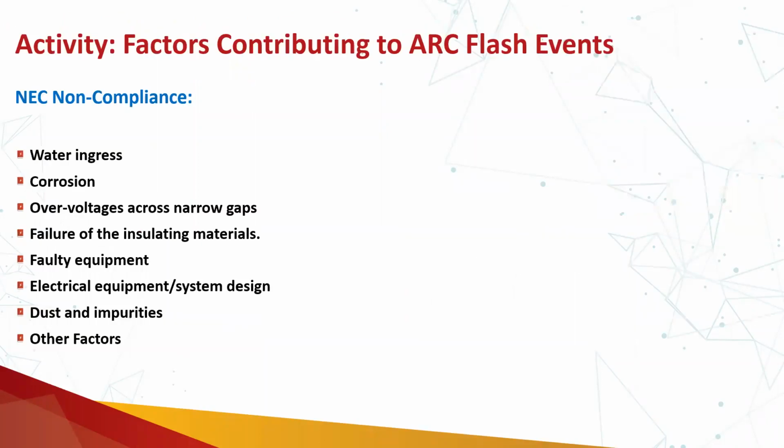If we try to map those things as per NEC non-compliance, NFPA 70E non-compliance, or NFPA 70B non-compliance, you are going to find that there could be a number of factors which could be common in one standard and also in another standard. For example, say you found that this arc flash event occurred due to water ingress. So what actually caused the water ingress? It was due to poor design of the equipment or poor selection of the equipment.